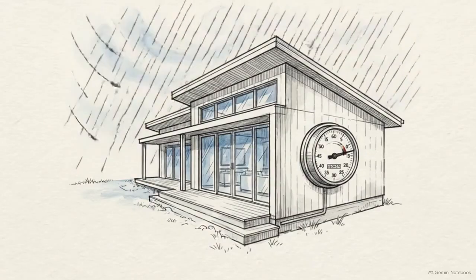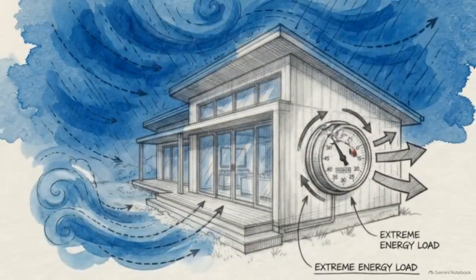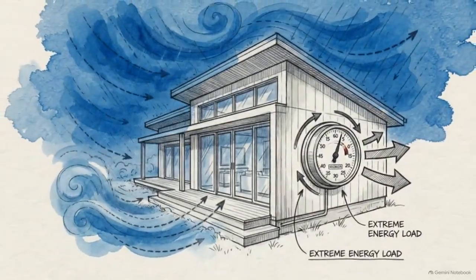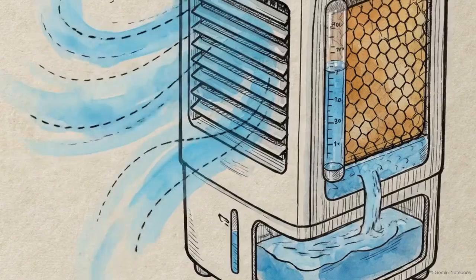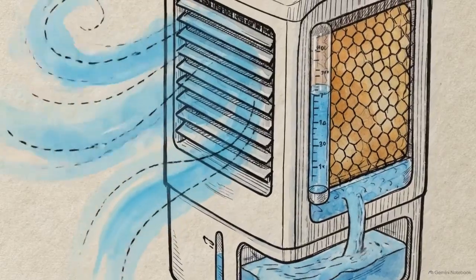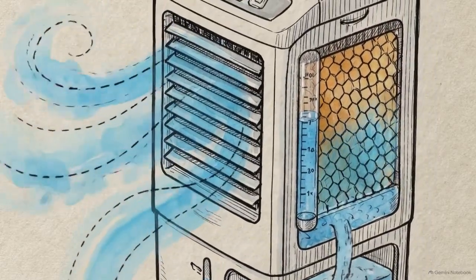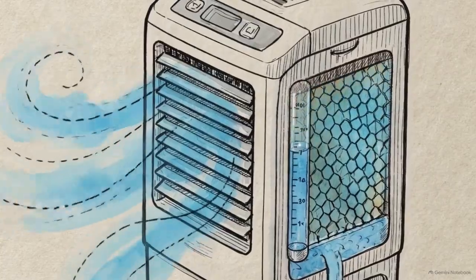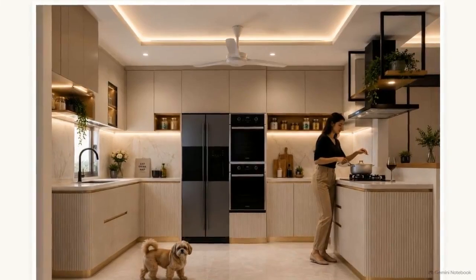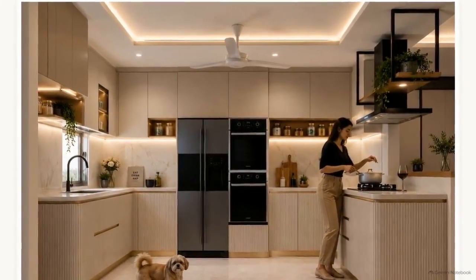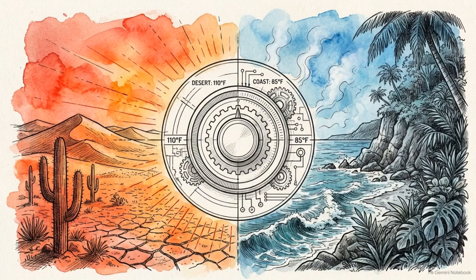This is the reality for humid coastal environments, where dehumidification is mandatory, and you are prepared to accept the higher electrical tariffs. If your local climate is hot but dry, and your home allows for excellent cross-ventilation, the logic points in a completely different direction. Here, an evaporative air cooler provides intense cooling power and massive electricity savings, provided you stay on top of the regular water maintenance. And for transitionary spaces, mild weather periods, or tightly constrained budgets, a properly placed fan remains a highly effective tool for physical comfort. The most effective cooling strategy relies on equipment that operates in sync with local climate physics.